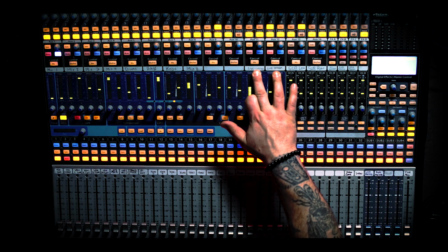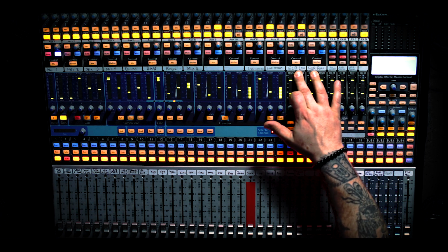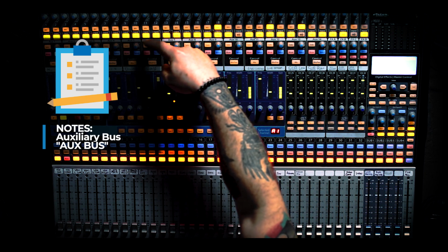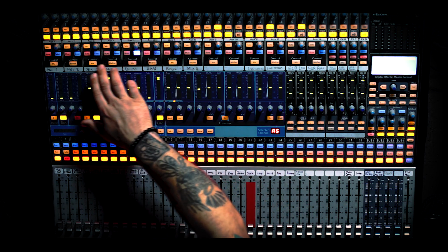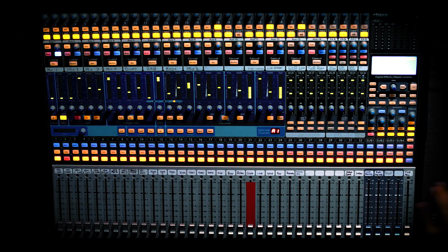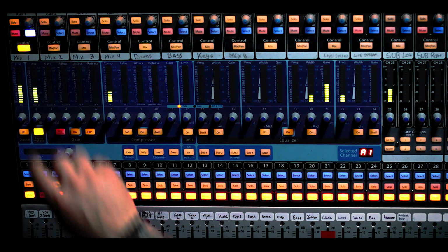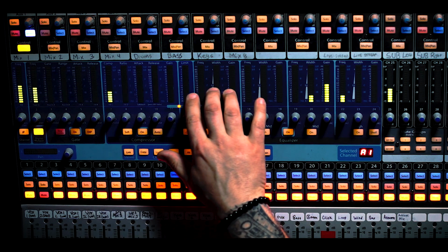Our live stream, in-ear mixes, and subwoofers are all routed through what's called an auxiliary bus. Each aux bus is assigned or connected to a specific destination. For instance, we can select aux 1 and see that it routes to the in-ear monitor mix of the vocalist on mix 1. By selecting this channel's mix button, we can mix the levels of the channels just like mixing effects.